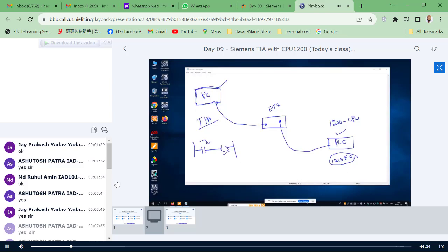So now this particular PLC output, I will connect it to one lamp. The lamp is connected, positive and negative. Now for this lamp address, you can write one simple program. You have to download it to the PLC and the lamp will be on. This is your field instrument, right? This is your RTU. The network is Ethernet, you can use the TCP/IP protocol. Normally they call it Profinet. This is the protocol. Got the idea? So this is the way we are going to write a program.